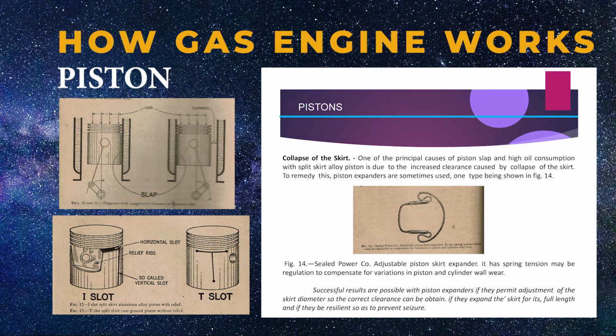Successful results are possible with piston expanders if they permit adjustment of the skirt diameter so the correct clearance can be obtained, if they expand the skirt for its full length, and if they are resilient so as to prevent seizure.